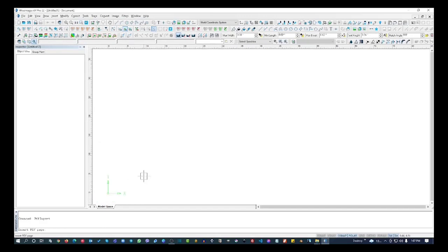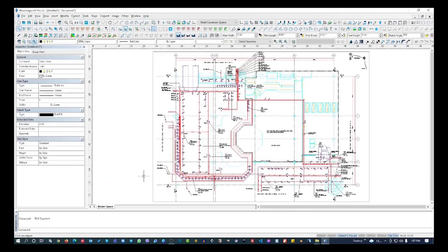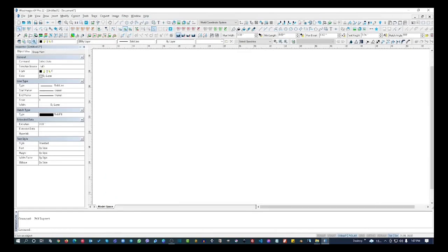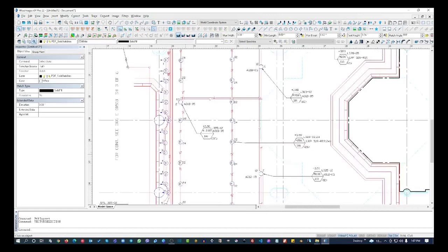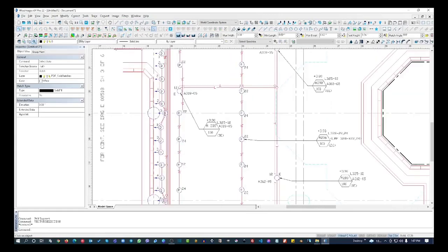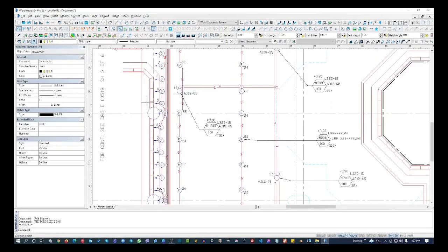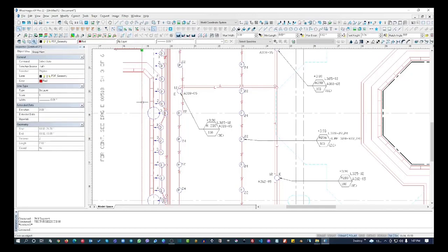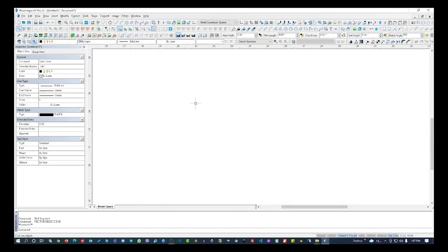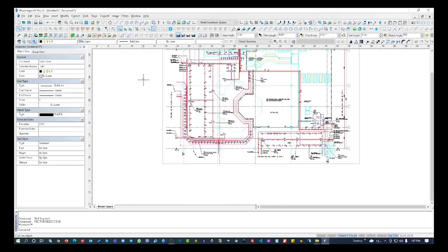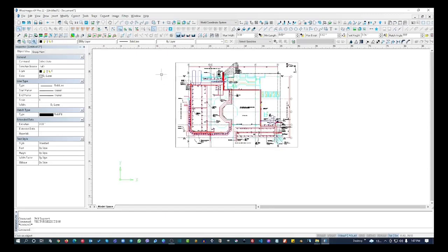So now it will take some time, and it will actually convert this whole PDF into CAD. Basically I can select these entities, these objects, and I can work on them, right? So I can select and work on those objects. So this is basically how PDF can also be converted into vector, and you can use the PDF objects.